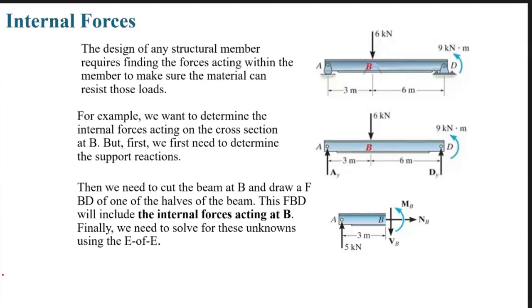From shear force diagrams, we can find shear stresses. Then from the bending moment diagram, we can find the bending stresses. By combining them and finding the principal stresses, we find which cross section is critical, which means we should add any area that reinforces that part or use another material. So before designing, the first step is to find the shear force and bending moment diagrams.